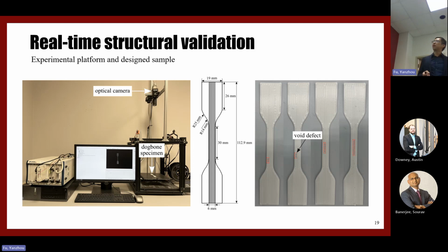So in order to achieve one of the purposes, like the cyber-physical defect detection, we designed different defects, like different defect lengths and defects on different positions. So here are the samples with defects. There are 3 different defect lengths and different positions. So the red rectangular marks are the defects. So this is the seeded defect we designed before the sample is printed out.